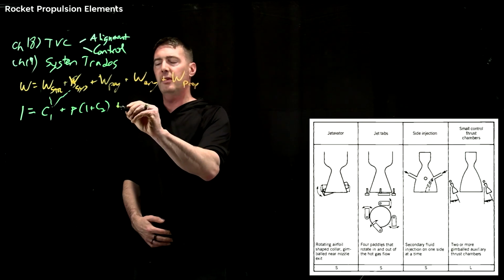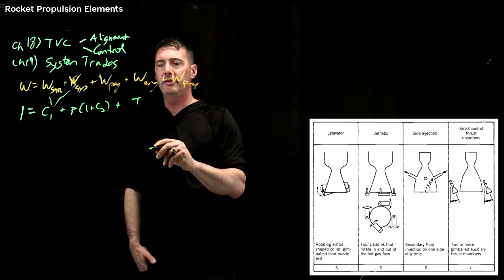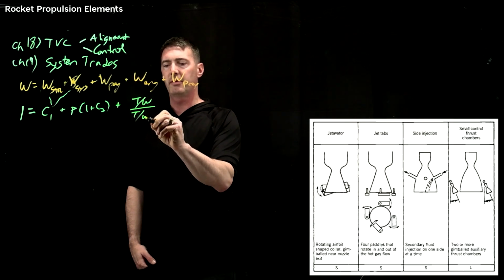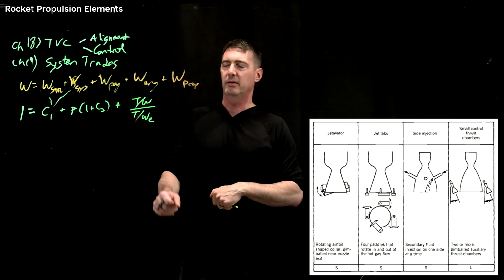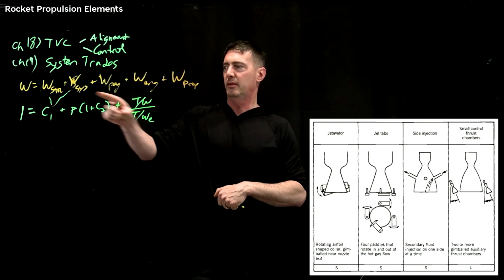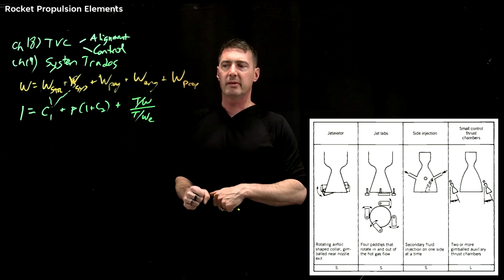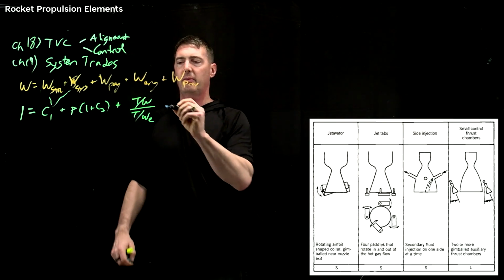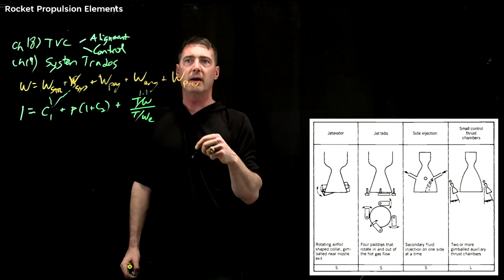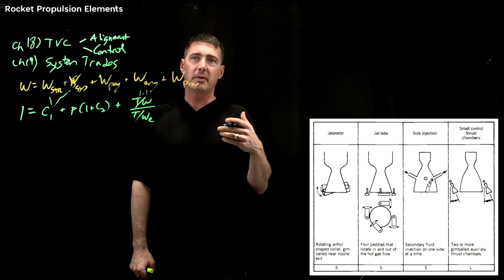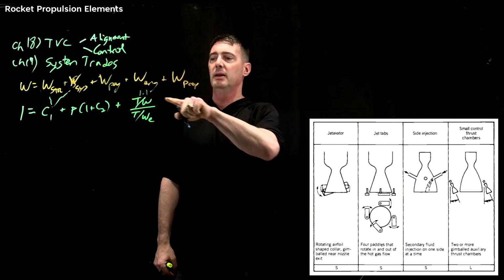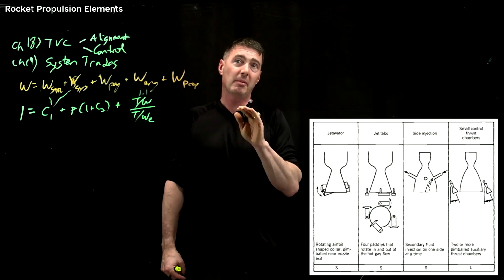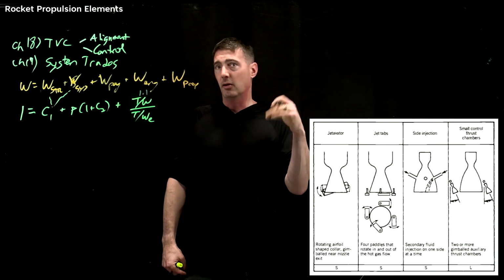Engine. Usually what you do here is you say this is thrust to weight of the vehicle, divided by thrust to weight of the engine. So you can see the thrusts cancel out, and then the weight of the vehicle was there. Now on a rocket, as a reminder, the thrust to weight of a rocket may be 1.1, but also the thrust to weight of something going supersonic, wearing my Venus hat, usually you have to be over 1 to get through the sound barrier. So it's the same number whether you're trying to be a supersonic aircraft or a launch vehicle.